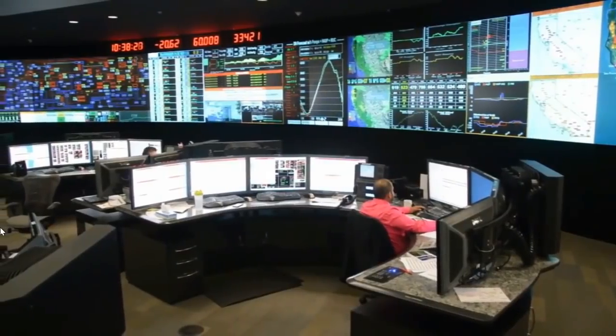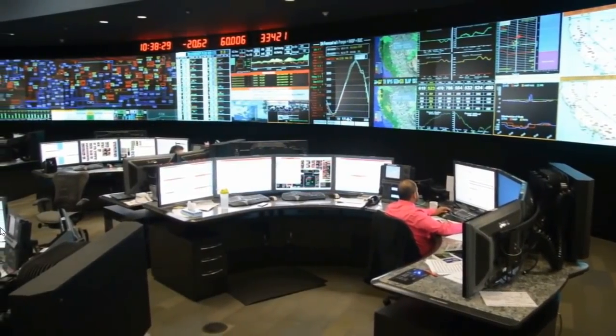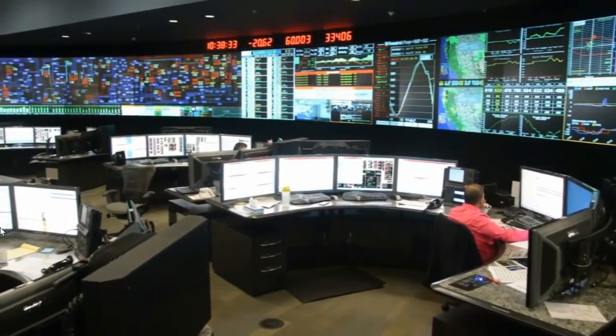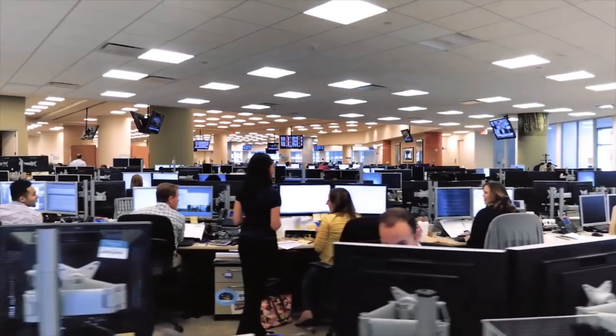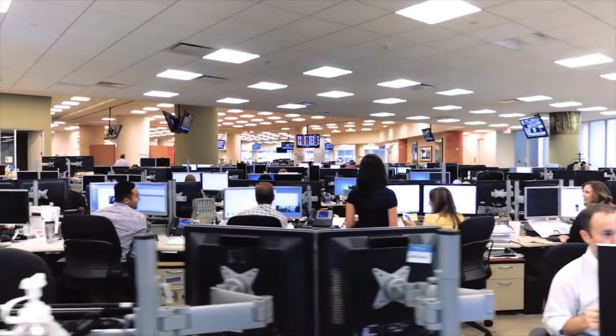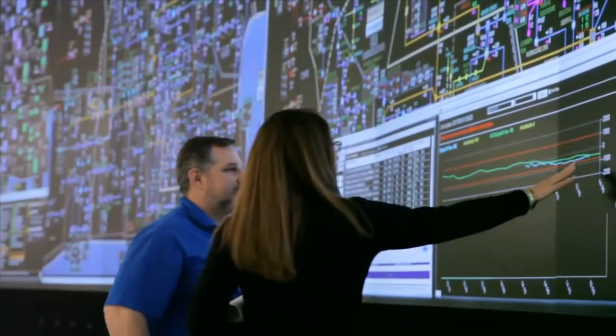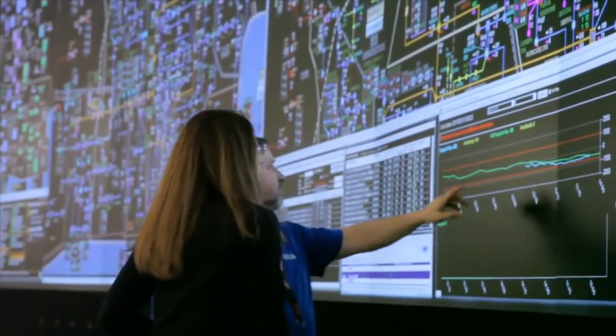As millions of people switch their lights and electric appliances on and off, thousands of generators must exactly match the load. To achieve this, power companies forecast loads and buy electricity on the day-ahead market and on the spot market, while grid operators contract balancing power to compensate the forecasting errors.